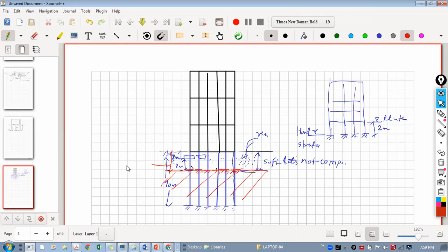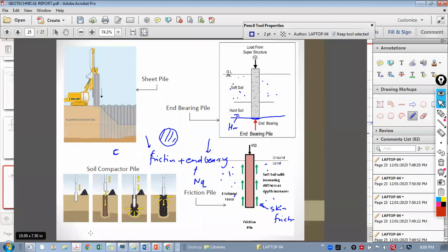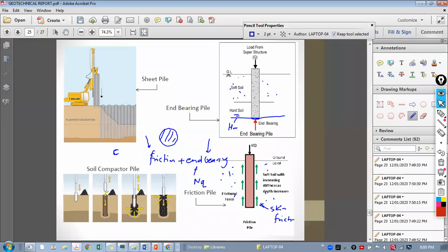Generally, I would say go for 3 meters to 4 meters, which will be a conservative approach and will be good because you may not know what is happening on site. So 3 to 4 meters we generally take. 3 to 4 meters means the height of a floor, for example. So this way we can decide. You can say this is soft soil, this is hard soil. So this will be my location of fixity in modeling, right?